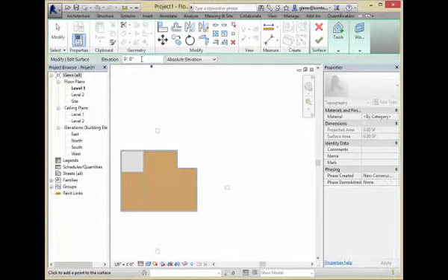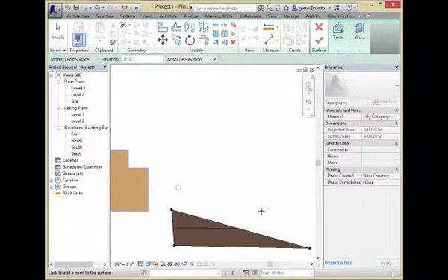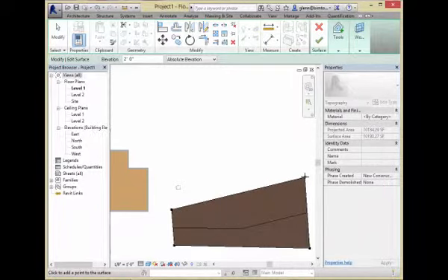Here's how points work. Every point has some sort of elevation to it. So if I want to create a bit of a hill, I can say that the front of the hill is at 0. I've placed a couple points at 0. This could be the bottom of the hill. If I want to have something that goes further up the hill, I'm going to place a couple points at maybe 2 feet high. I'll put one over here, and I'll put one over here. As I place points, I'm saying in the topography at these specific elevations, that's the height that it should be. It'll figure out what the contour lines need to be to make that happen.